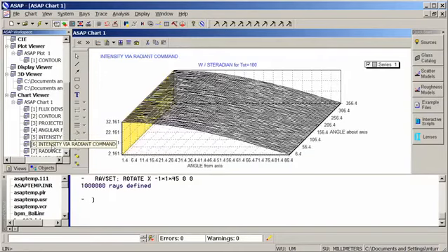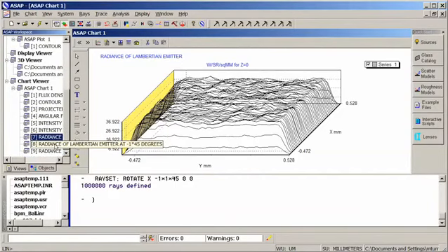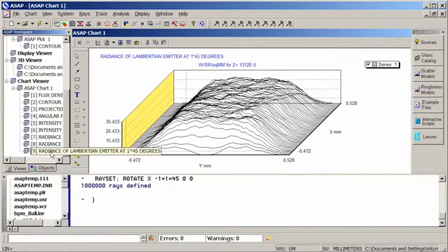With the radiant command, what we can look at is the far field incoherent intensity of our Lambertian source, and we can see the expected fall off. And here's the radiance in watts per steradian per square millimeter. And what we do now is rotate the source plus and minus 45 degrees, and again calculate the same information.